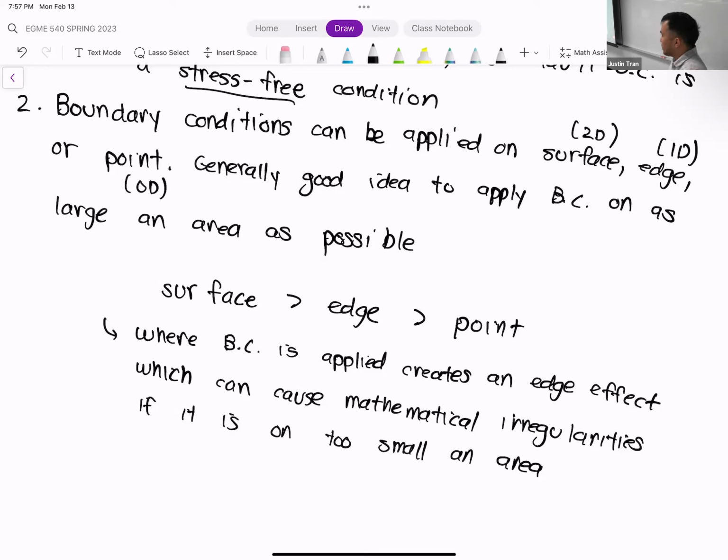That's basically the same thing as taking a needle and putting the weight of, whatever, 18 bowling balls onto that needle. And of course, that's going to have a very different physical effect than if you distribute that load all throughout. You're going to have a needle that pierces through the rack. And so you want to avoid those situations. Most of the time in a realistic situation, the load is distributed across an area. And so you want to make sure that you respect that in your simulation as well. And it leads to better mathematics too.